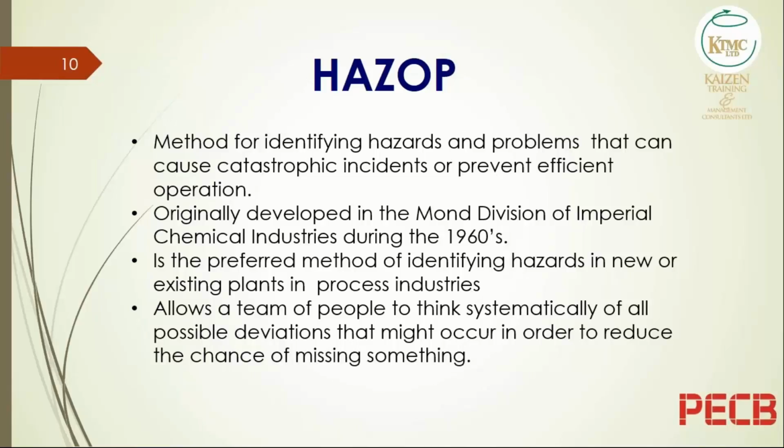And I must say that a key requirement in HAZOP is the development and availability of piping and instrument diagrams for the facility that is being considered, whether it is existing or it is a proposed facility that is at the design stage. The design intent is depicted in the piping and instrument diagram, and this forms the basis of the analysis.